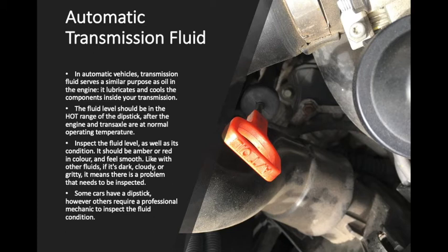It should be amber or red in color and feel smooth. Like with other fluids, if it's dark, cloudy or gritty, it means there is a problem that needs to be inspected. Some cars have a dipstick, however others require a professional mechanic to inspect the fluid condition.